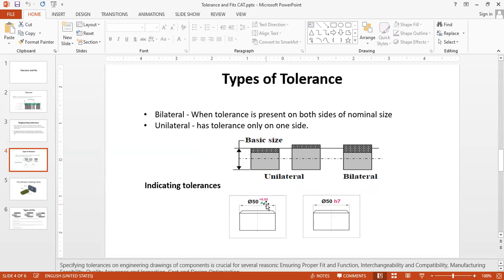In some machining, like grinding processes, the variation of the dimensions is very low, but if you are doing hand sawing or filing, the variation is very high. According to this, we can identify which process can be used, and this is needed to reduce cost of design, or for design optimization.